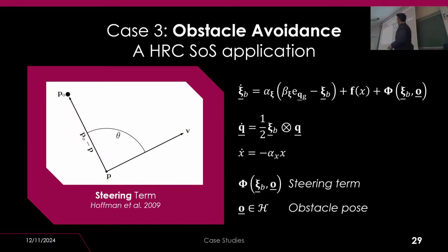So the actual point, our position, our orientation as well in the manifold of rotations, would be steered away from the obstacle. I did not prepare a slide about the actual theory behind, but it's basically an equation that takes the cross product in both position and orientation tangent spaces from the obstacle to the velocity, so as to obtain the steering away from the obstacle.